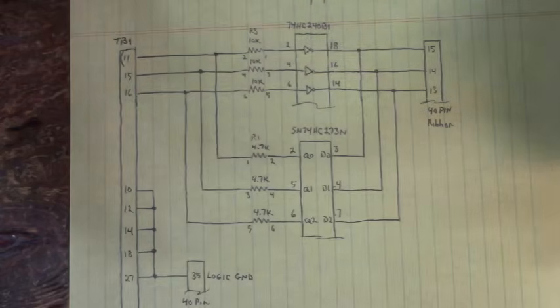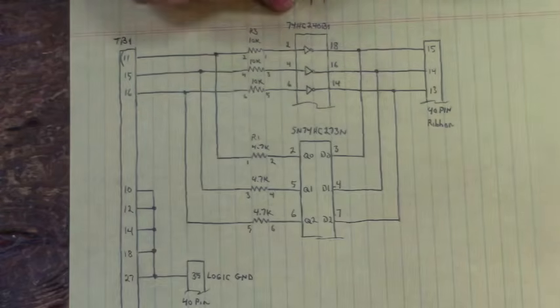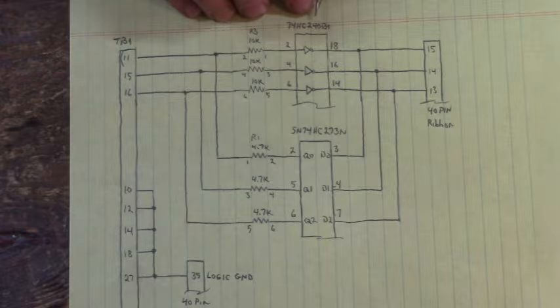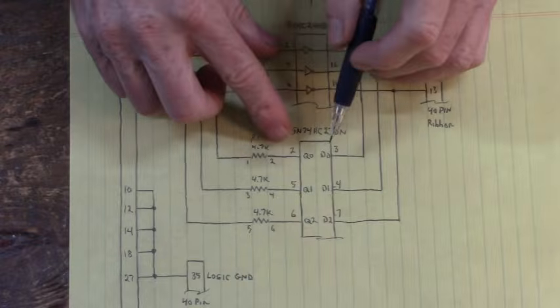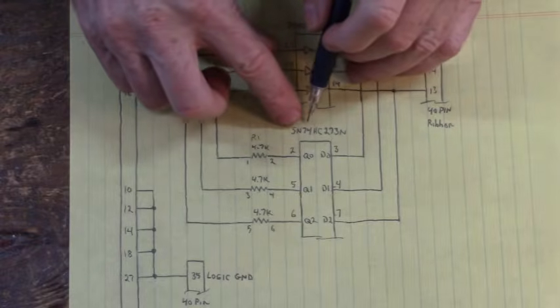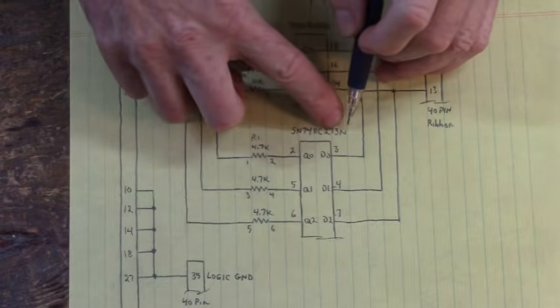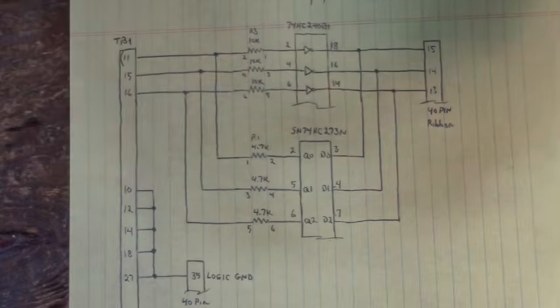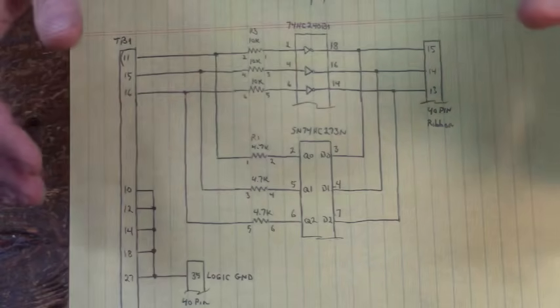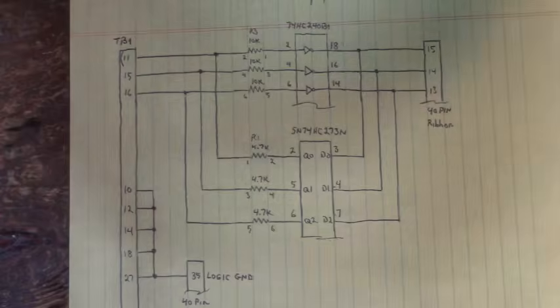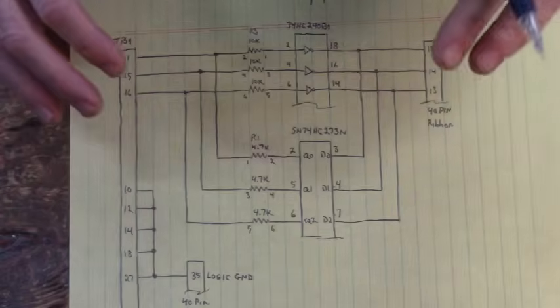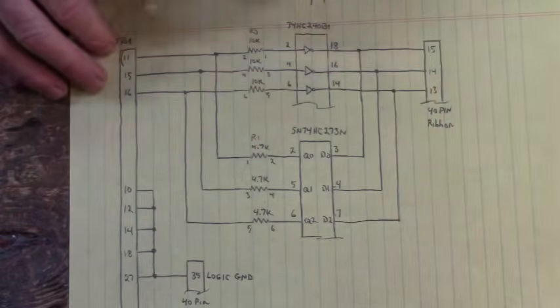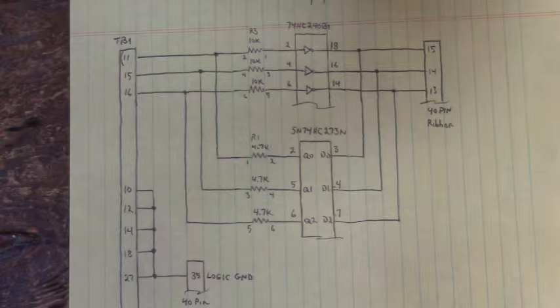And so I mapped the circuit out, and right here we have a 74HC240B1. That's an octal buffer driver IC. And here we have an SN74HC273. That's an octal D flip-flop. Now, this is the interesting part. The software, the saved parameters set whether this output is active high or active low.